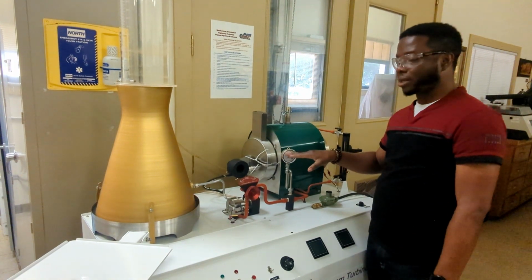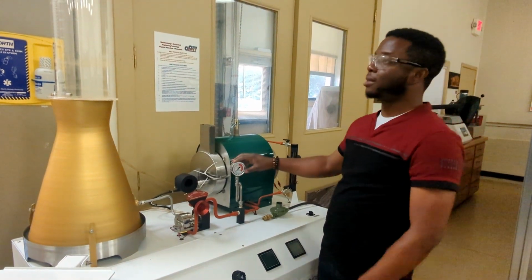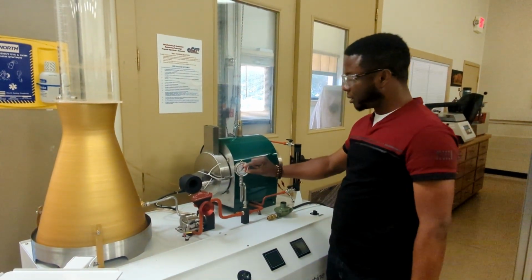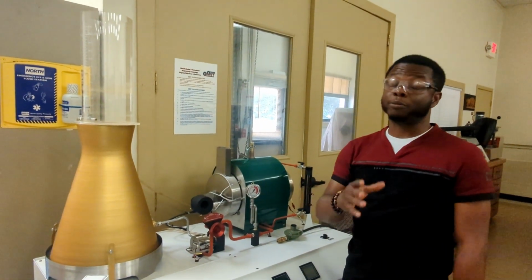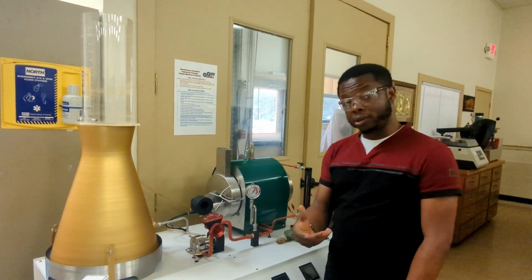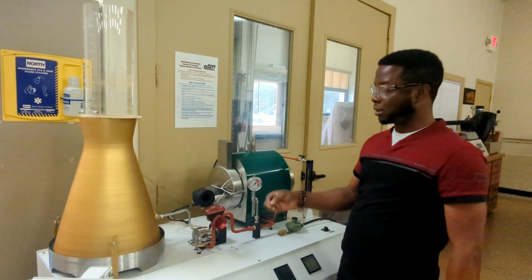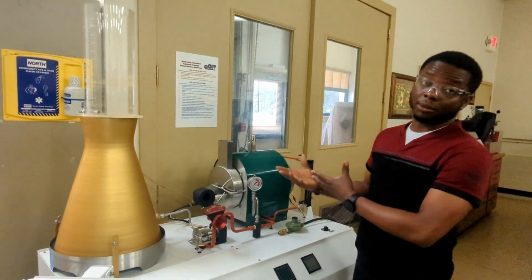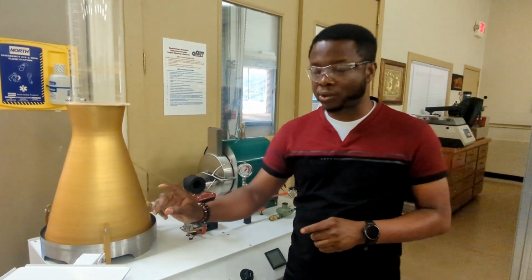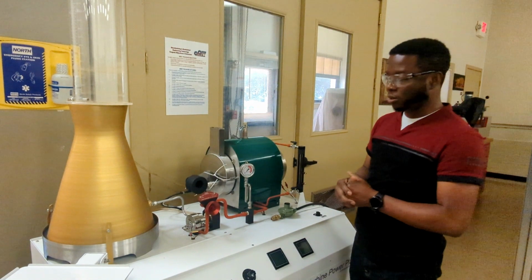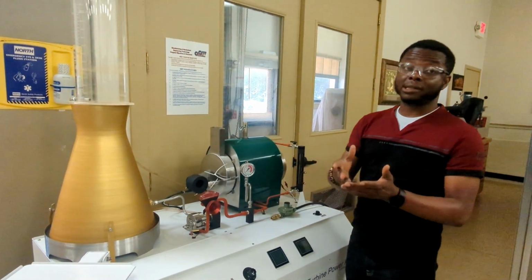By the time the pressure gets to 120 psi, we can see the indicator starts having some disturbances. At that point you start releasing the steam admission valve gently to allow entrance of steam. That little entrance of steam, you can also monitor from the system. What are we trying to monitor? We are trying to monitor one, built-in pressure in the boiler, and also elevated temperatures.